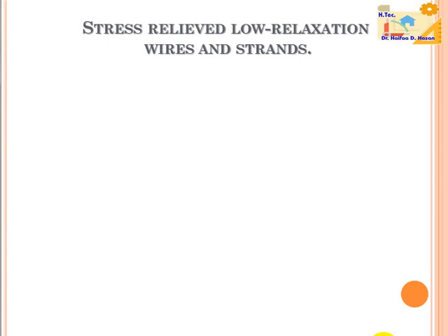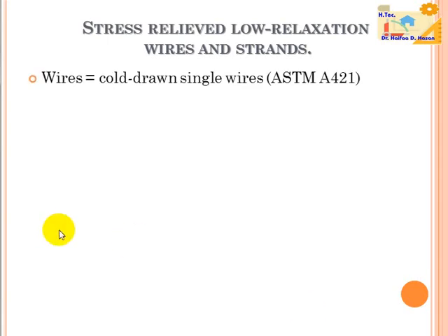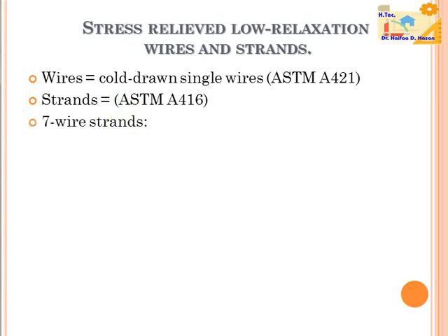Stress relief and low relaxation wires and strand. ASTM A421 was for cold drawn single wires, and for strand the ASTM specification A416 covers 7 wire strand.